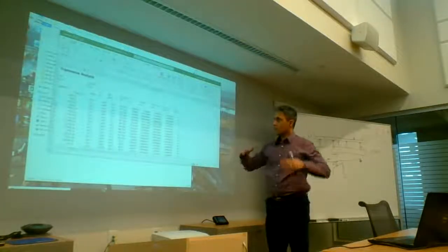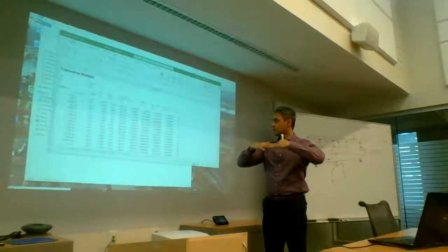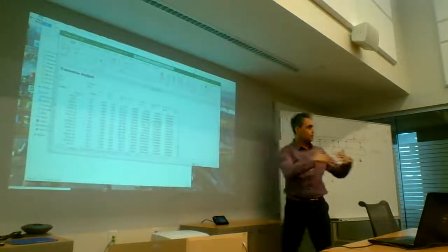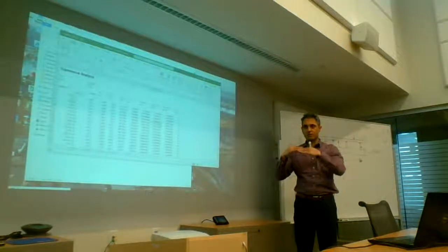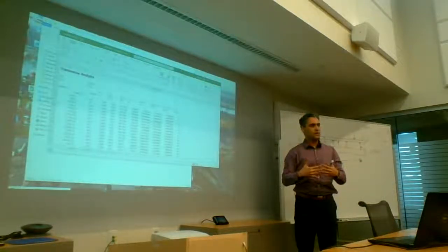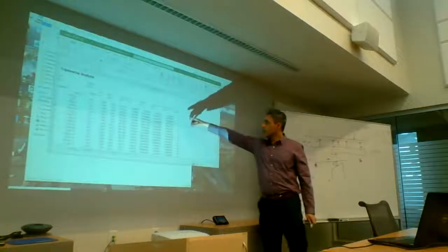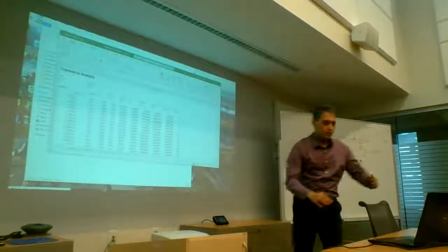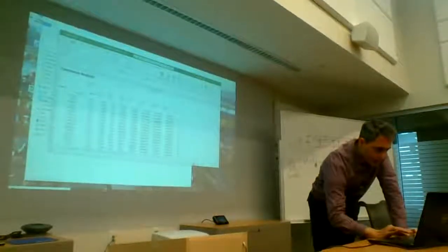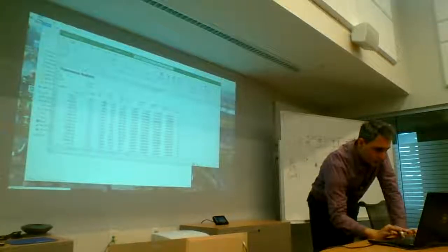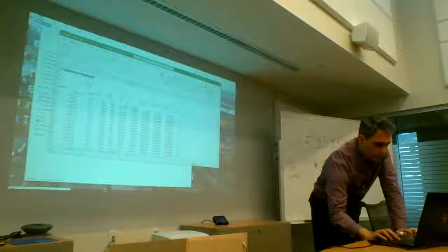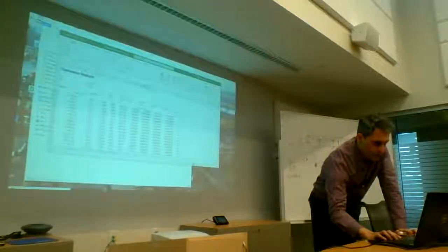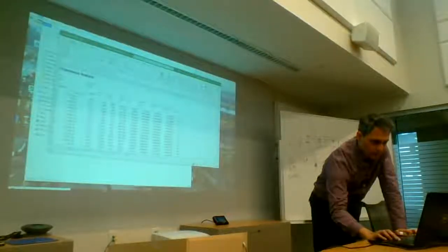So what you're seeing here is the transverse analysis, the load is not uniform. The load is only uniform per section. So the more you discretize it, the better results you're going to get. So then you go into your model and you apply these loads. And when you see up here, you will see that these are pretty simple formulas that you can just multiply around.